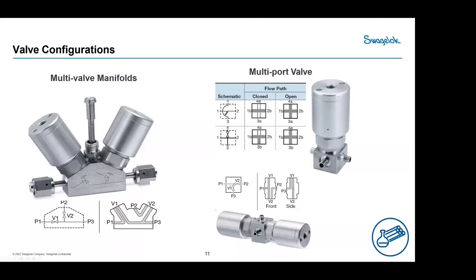When we look at a single valve in improving the purgeability, it doesn't have the purging capability on its own. Obviously, it has to have a circuit introduced into it to be able to purge it, or it will be cumbersome to purge it and be able to use it. But when you add another valve in the loop or another flow circuit in the loop, we have just added a quick purging ability. By adding another valve or circuit, now you have that purge capability built into the system. And you can do it two different ways.